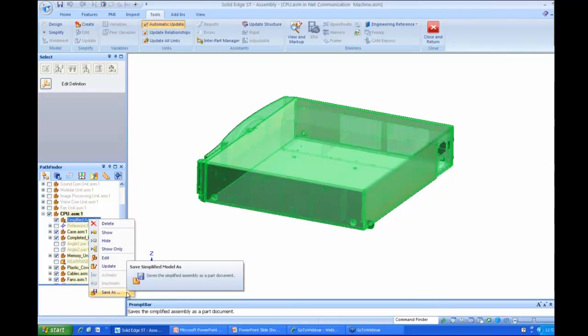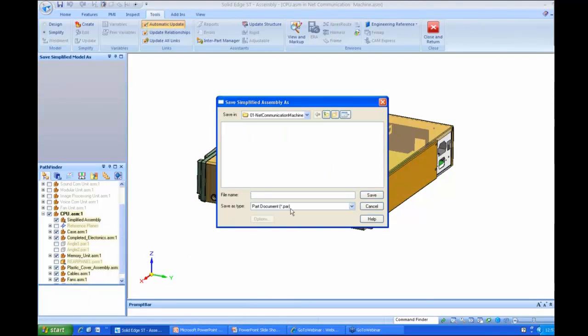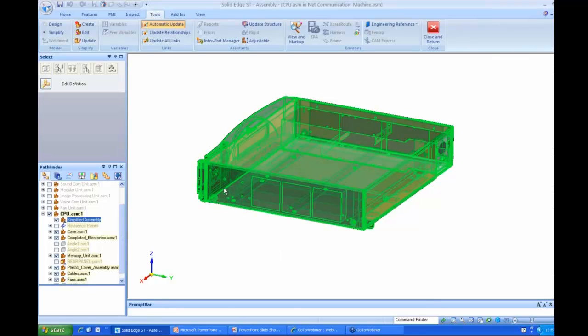We're talking about simplifying for large assembly purposes, but another question that comes up every once in a while from our users is, how do I save out this sub-assembly, or even the top-level assembly, without giving all of my intellectual property to my customer? We always get that call from a customer saying, hey, I buy this off of you, can I have a CAD model to put in my plant layout? Well, this would be the way we do that. We can simplify it and get the outer structure of this, which we did with the simplify process there, and we could also exclude some other parts, some other intellectual property. And right here from the simplified assembly you see a Save As, and I can save that straight to a part file, or I can push that out as a neutral format to Parasolid. So just to point that out.